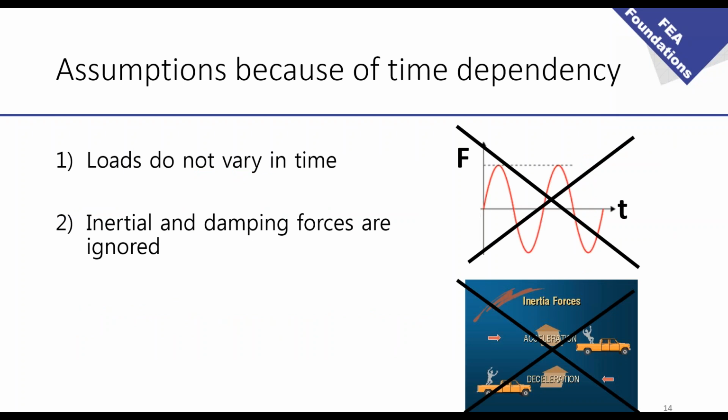The second set of assumptions is about time dependency. As I was telling, this is static, so loads do not vary in time. Here on the right you have a sinusoidal force loading, so you cannot consider this type of loading in linear static. The second is that you ignore the inertial and damping forces. So for example, acceleration, deceleration, you can think about Coriolis maybe. All these forces are ignored in linear static.